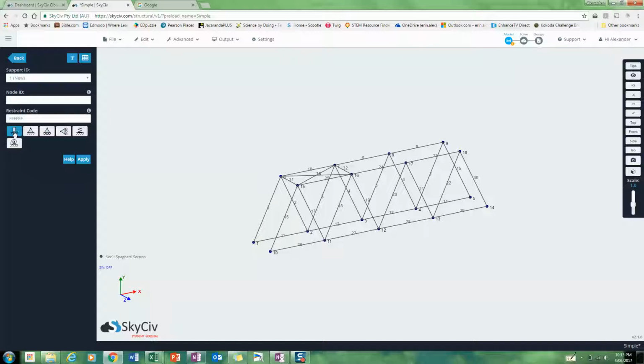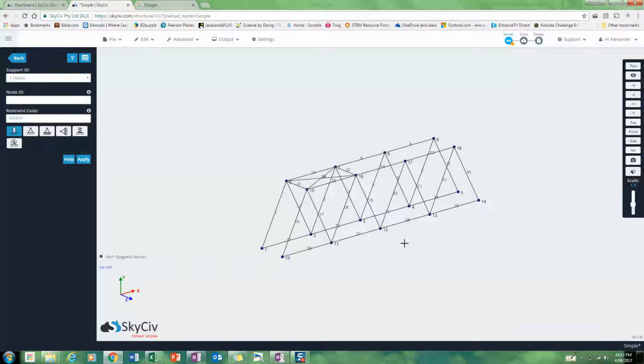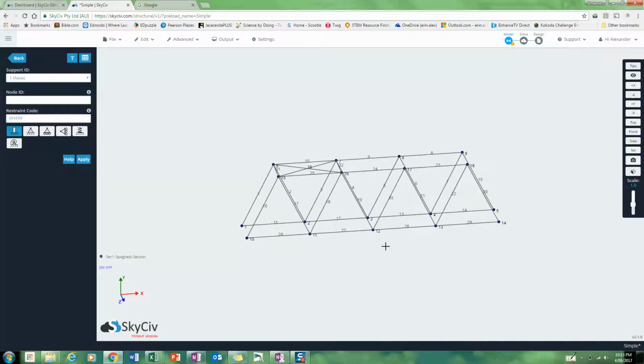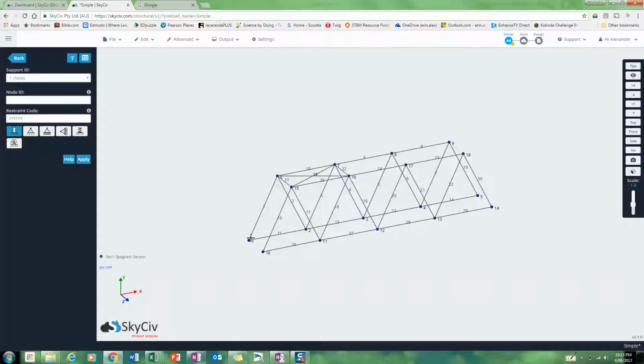Using the completely fixed support at both ends is not going to be very accurate to what we will be doing, because we're just putting our spaghetti bridges across two desks or across a loading system platform. The points of contact are not actually fixed in any way. We're not gluing them down to the desk. So the bridge is able to flex and move relative to the desk a little bit.